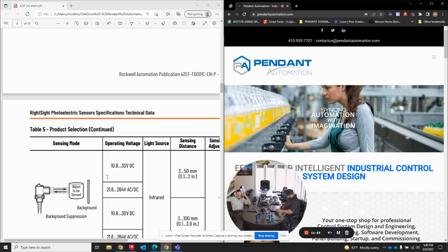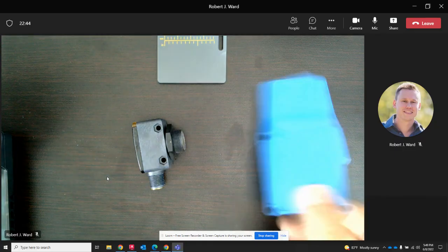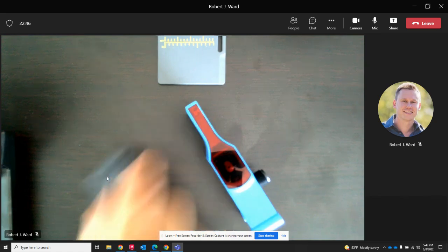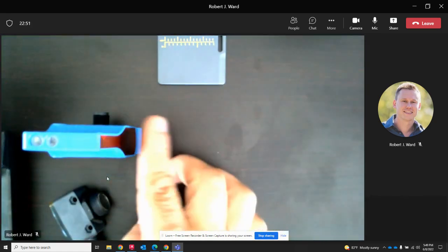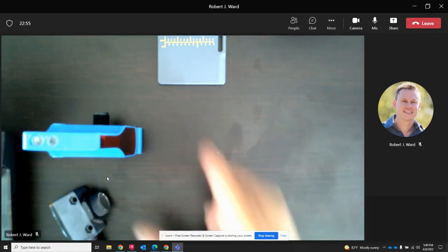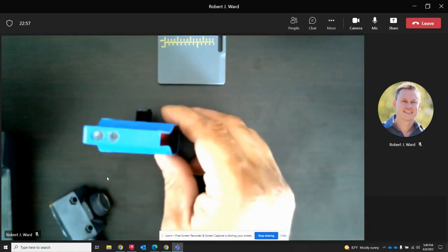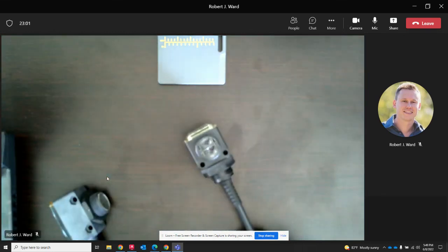If I were able to share our screen again, this guy right here is actually a diffuse sensor. It is emitting and receiving light off of a fixed object without the reflector. So this one that looks up between the rollers is diffused. Like you said, back in the day, we would put a sensor straight up to the rollers like that.